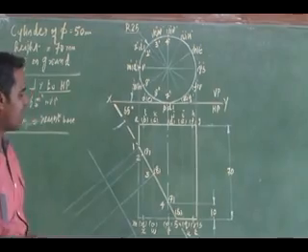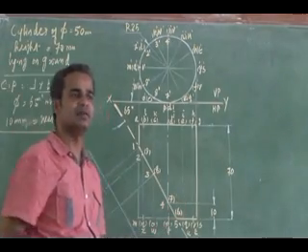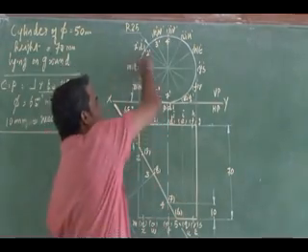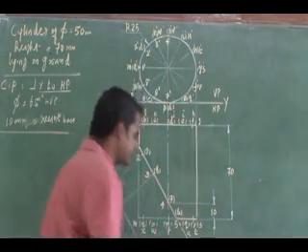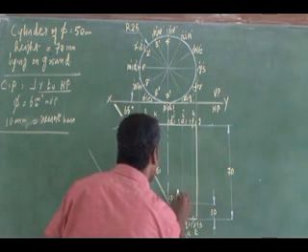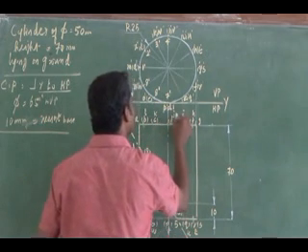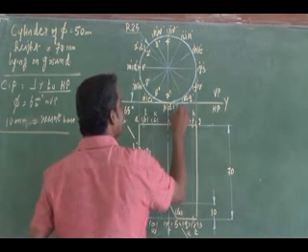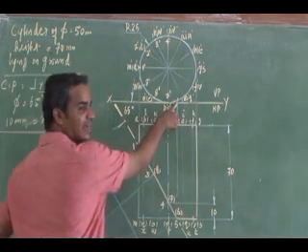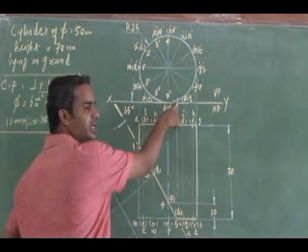Right. What about this? How can I mark this 5 and 6? It is on the base. Base is seen as a circle in the front view. So this 5 and 6 I can project directly to the front view, wherever it cuts the circle in the front view. So where it cuts the circle in the front view, that is my what cutting point?